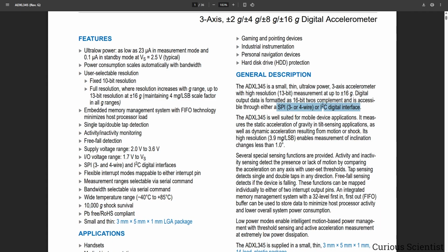And also, if we still want to compare these two protocols, a big difference is that for SPI you can select your chip by using the chip select pin on the slave device. But with I2C you can encounter a problem where similar devices have similar addresses. For example, displays typically have the same address and you cannot really change their addresses. So if you want to use one microcontroller with one I2C bus and, let's say, 10 identical displays, you cannot really do it in an easy way.